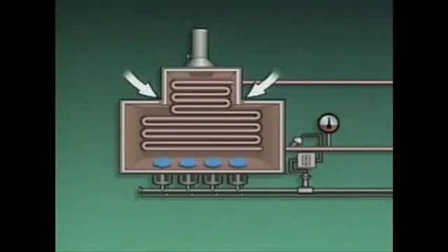If air leaks into a furnace, it can lower the temperature of the flue gases inside. An air leak can also lower the temperature of the tubes and the outlet temperature of the process fluid. If this happens, the temperature controller will call for more fuel to bring the outlet temperature back where it should be. Since more fuel is needed, the cost of operating the furnace goes up.